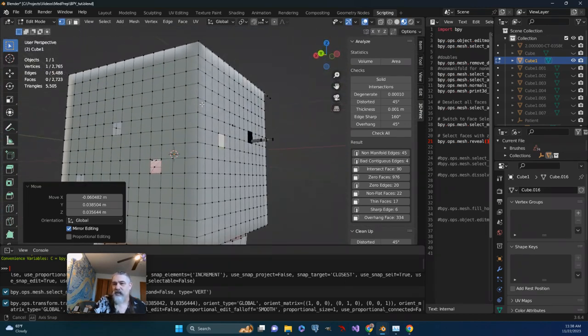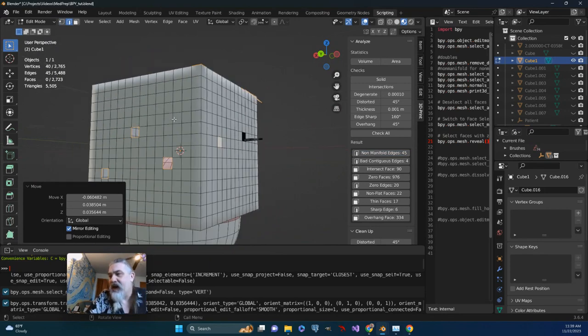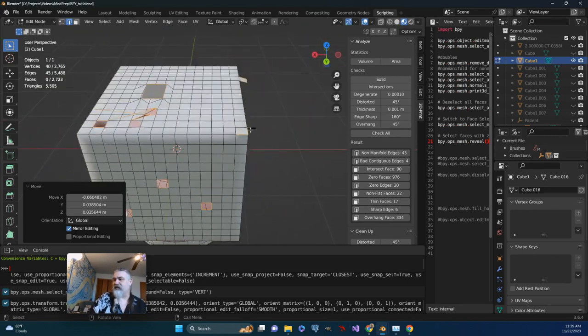I've got a number of holes in the mesh, so that would be part of the problem as well, because in essence, this is a non-watertight object. So it gives you kind of a sense. Basically, what we're looking at for non-manifold edges is sort of this impossible geometry that makes a mesh porous or creates inconsistencies in it.